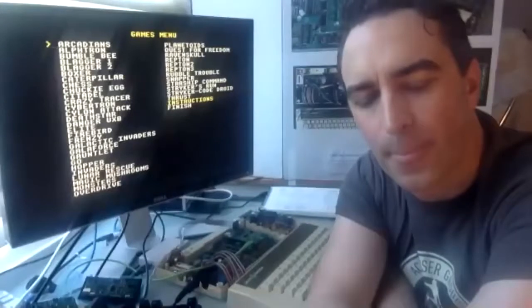And I hang things off, and they seem to be so bulletproof because I'm such a klutz. I put the 3 volt into the 5 volt and expect them to fry, and they just survive. So they're probably worth a look, because with some of them you get 24 pins in a package, and any of those pins can go in either direction. So they're well worth a look.